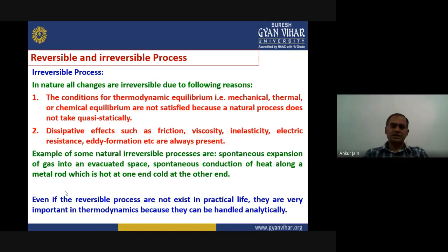Okay. The second one is dissipative effects such as friction, viscosity, inelasticity, electric resistance, eddy formation. These kinds of dissipative effects always exist with all natural and practical processes. Here are some examples. For example, if we allow a gas to expand spontaneously into an evacuated space, if we take some amount of gas in one box and we open it immediately, what will happen? This gas will spread throughout the room, and it is not possible to bring all the gas molecules back into this box. That means this is an irreversible process.